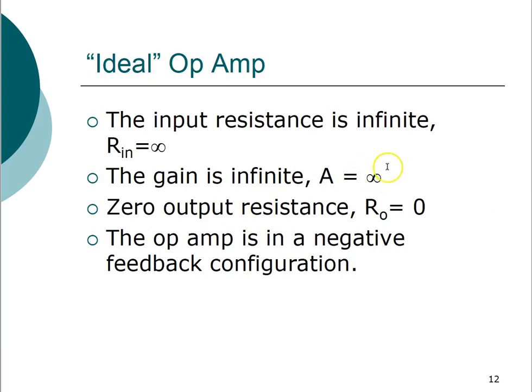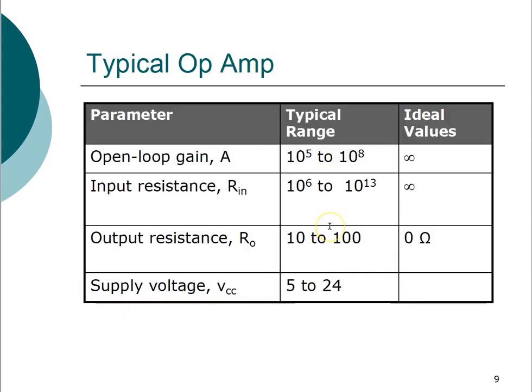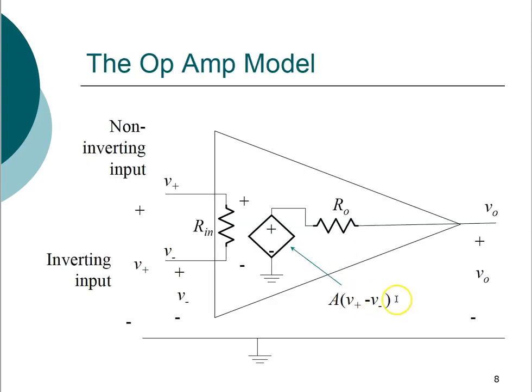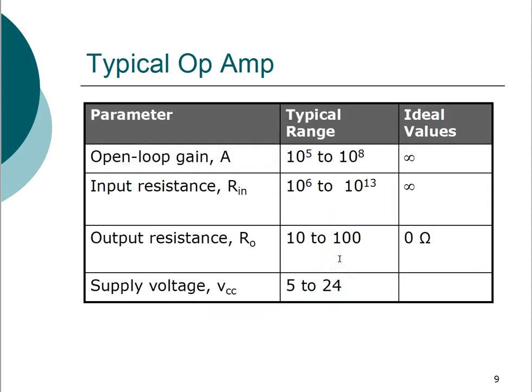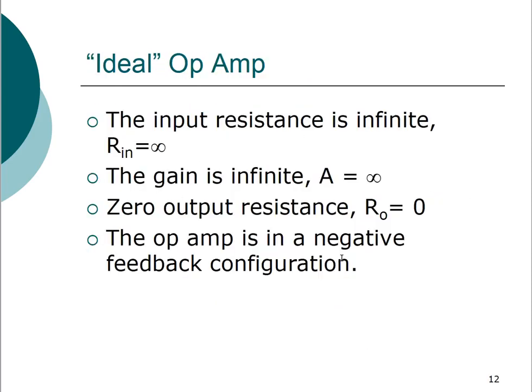It means that your V plus will be equal to V negative. So think about this. Going back here, if this is infinite, then that means your V plus is equal to your V negative. So that's why in an op-amp, which you will be seeing in the lab, you will see both the supplies are of the same power. Okay.